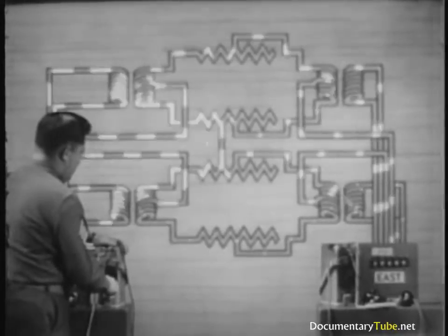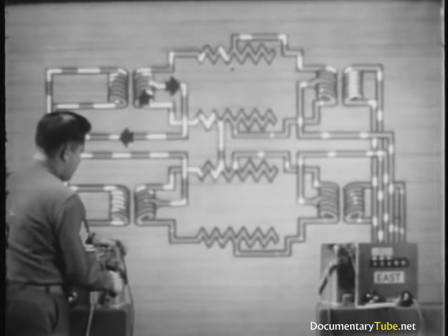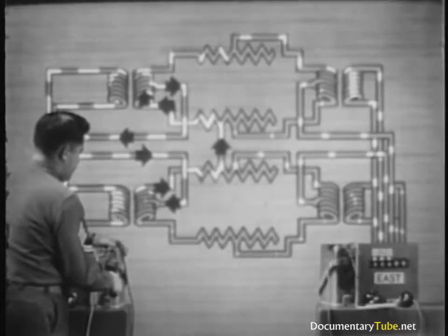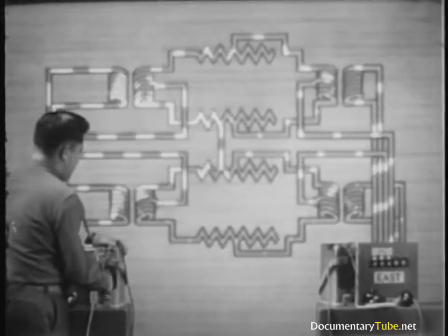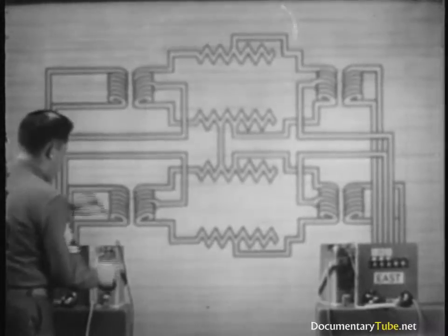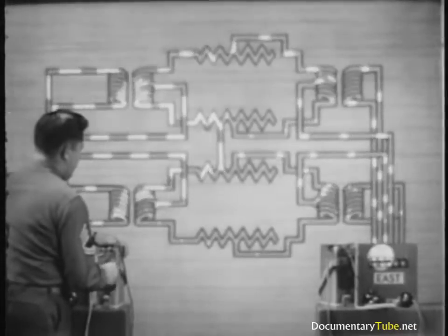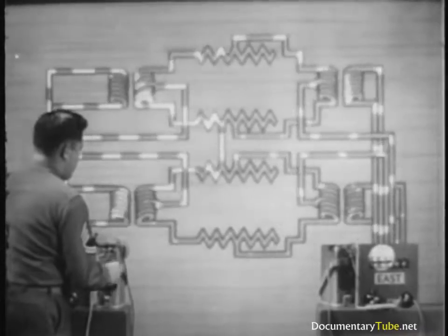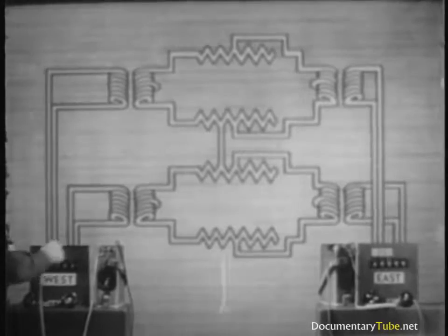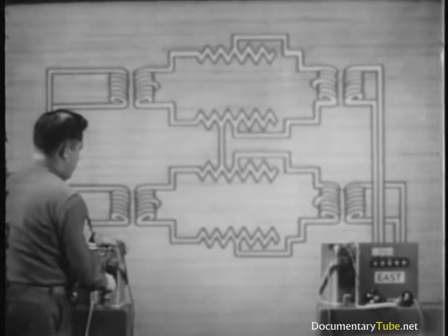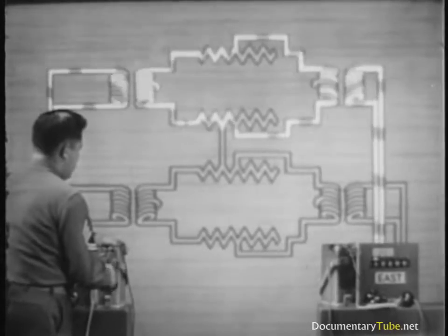Ringing on one of the side circuits, we can see that the current follows a similar path and causes interference in the other 2 west drops. And here again, the circuits are affected at the east end. We've got 3 circuits interfering with each other again. But this time, 2 can be made to work fairly well. If we cut out the phantom connections at both ends, the 2 side circuits can be used. Actually, we no longer have a phantom group.